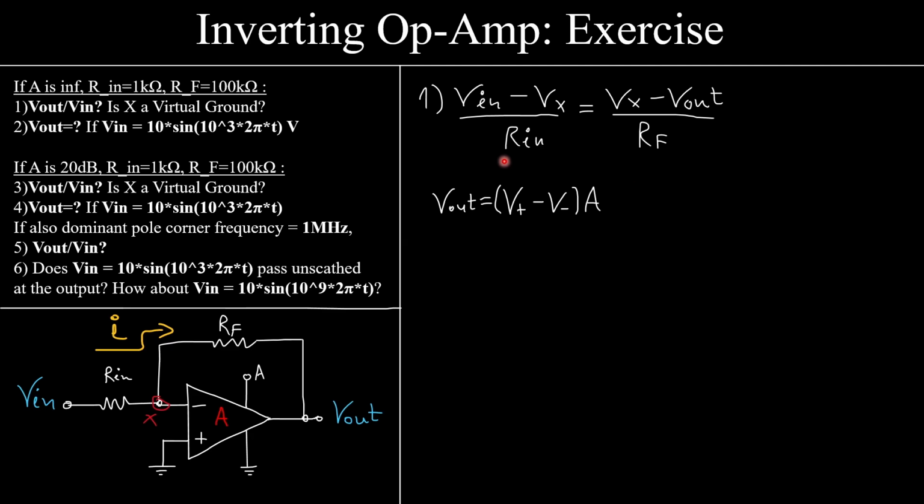I know this equation holds true for all op-amp configurations. Now in this equation I have the output and the input voltages over here and the gain. I know that because I have a negative feedback configuration, I would have a finite output, a small output. But the gain is infinitely large, alright, it's infinite. Therefore, that means that V plus and V minus, the two input voltages over here, must be very, very close to each other. This difference must be very close to 0, alright?